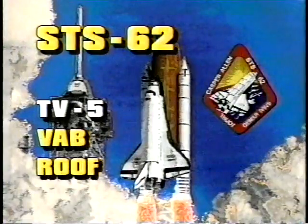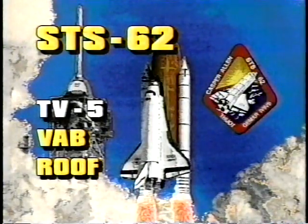As we continue to watch replays of this morning's successful launch of Columbia, the crew aboard Columbia is in orbit, currently at an altitude of 66 nautical miles in a 156 by 44 nautical mile orbit. Coming up in about 25 minutes, the orbital maneuvering system engines will be fired to circularize Columbia's orbit at 160 by 163 nautical miles. In the meantime, the crew will be busy configuring their systems on board to prepare for that OMS burn. That involves shutting down systems that were used during the climb to orbit that are no longer of necessity right now, including the auxiliary power units that provide pressurization of the hydraulic systems.